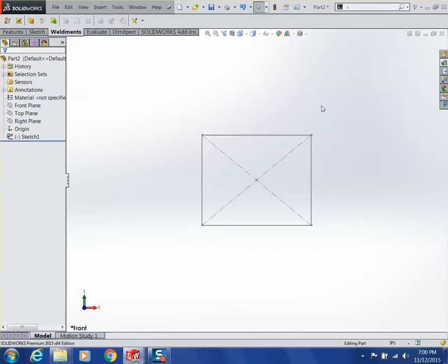You can do a Hole Stack, is the name of it. It's an assembly-level feature, so once you've got your assembly with 2 plates on top of each other, you can put a Hole Stack in. At that point you go through and pick, hey, I want the clearance hole in this plate, I want the tapped hole in this plate. You can set that stuff up that way.